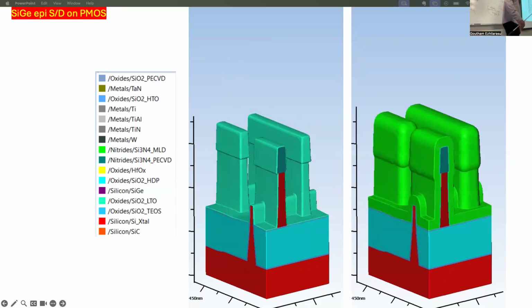Yeah. Next, this step is going to get a little complicated, so just follow along. You have to create the same way that in your planar MOSFET, right? So remember in your planar MOSFET, what you actually do is, once you created your gate. Also, one more thing I wanted to say is, there is also an implant step for creating the lightly doped drain region that I've not shown here, okay? So that part you have to do yourself because you need to calculate how much doping is needed for the lightly doped drain region.